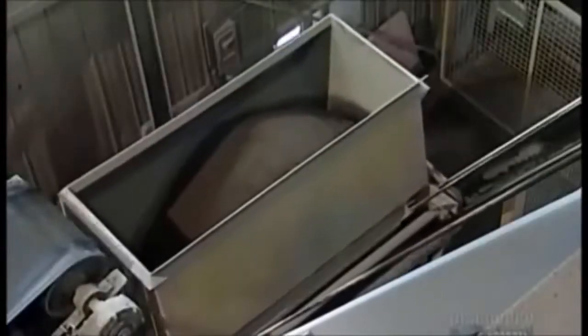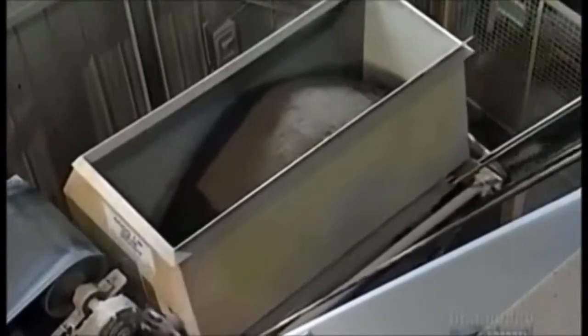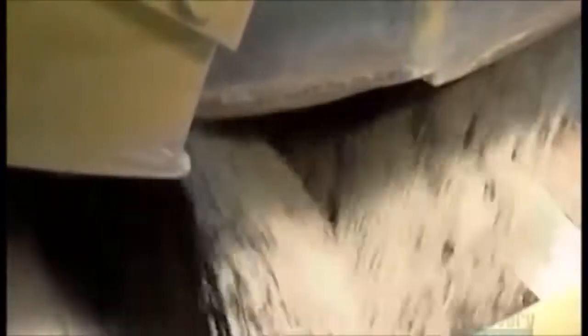Both are en route to the skip hoist. They spill off the conveyor into the skip hoist, which is essentially a bucket on rails. Cables pull the loaded bucket upwards. It stops about 9 meters up, just above a big concrete mixer. A trapdoor opens and dumps the sand and stone chips into the mixer.